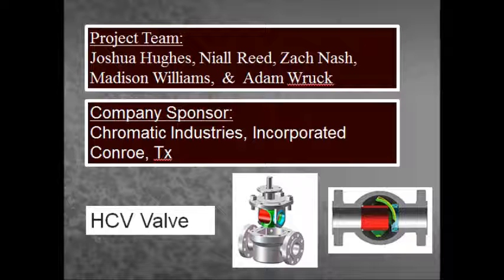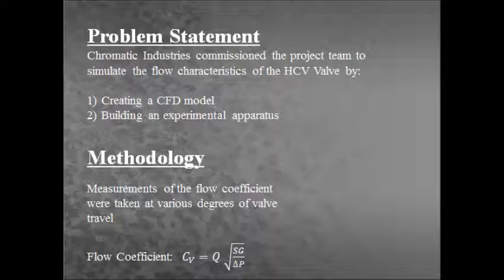HCV valve. For this project, both a CFD model and an experimental apparatus were built to model the flow characteristics through the HCV valve. The data collected during analysis was the flow coefficient, which is influenced by flow rate, pressure change across the valve, specific gravity of the flowing fluid, and other valve design qualities.